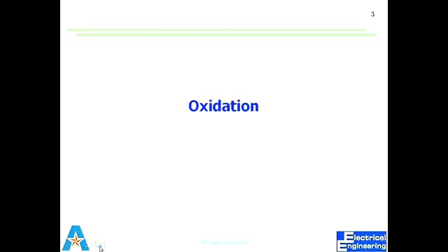You can etch it, or you can do diffusion. Of course, to do diffusion, we'll have to open that hard layer. We'll have to do etching first, but we can do something else. Etching is removal of material. We may want to deposit material at certain places only, right? But if I deposit something, it's going to cover everything.